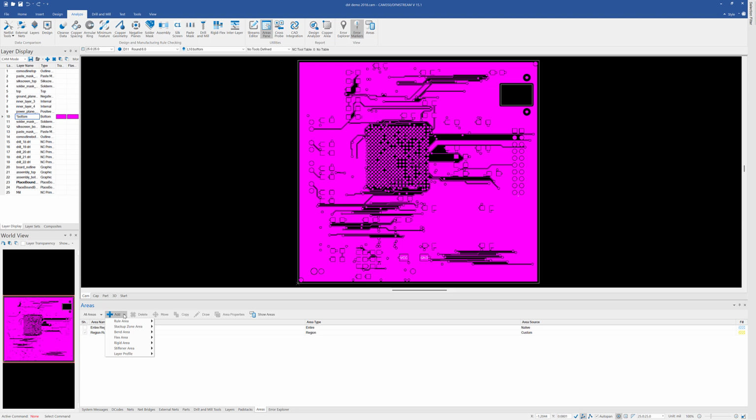I always call it reverse engineering when you're taking a rigid flex design that wasn't sourced from intelligent data and using Gerber and NC, because you're doing a lot of work to get all that information that was thrown away when the designer decided to output Gerbers instead of an intelligent format. This allows you to build that back again. You're doing that reverse engineering process, so this is handy for doing that particular process.